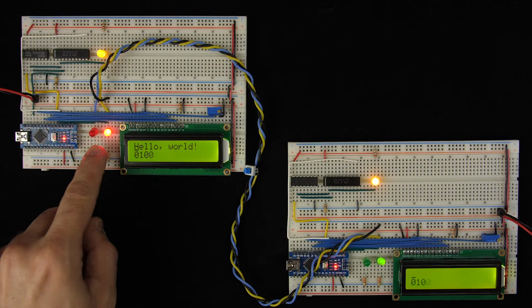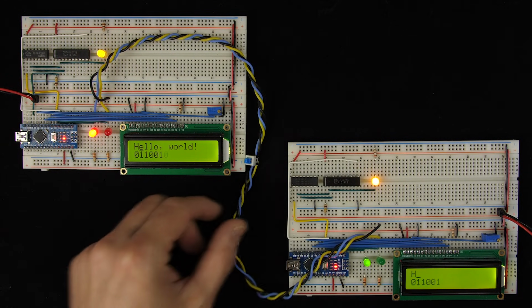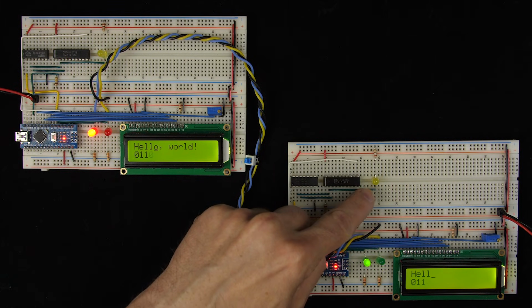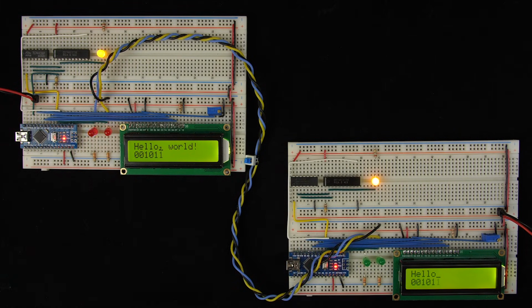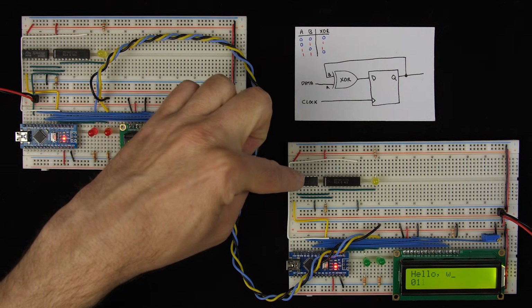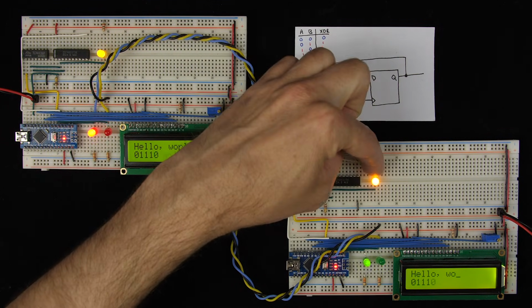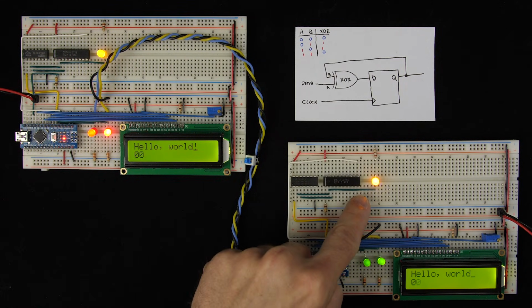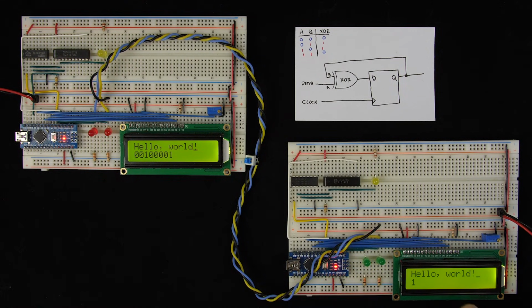When we're sending data from one computer system to another over a serial link with a simple clock and data protocol like this, I've shown you in previous videos how it's pretty straightforward to build a circuit that computes the parity bit. So we just have our clock and data coming in here, and we just have an XOR gate and a D flip-flop, and out the other side comes a parity bit that we can use to validate that our message was received correctly, or at least that certain types of errors didn't occur when we received our message.